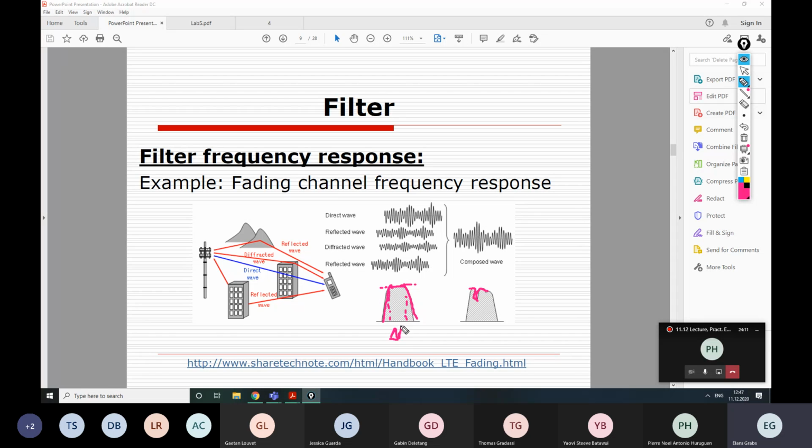So this is our frequency band, which affects our data transmission rate, as we have already discussed during our discussion of the Shannon theorem, information theory, and so on. And well, we need a more or less constant signal level in this band. Now, because of some distortions in the channel, this can be, well, not true. So that's meaning that a channel can actually be considered to be a filter too. Well, that's a model of a channel.